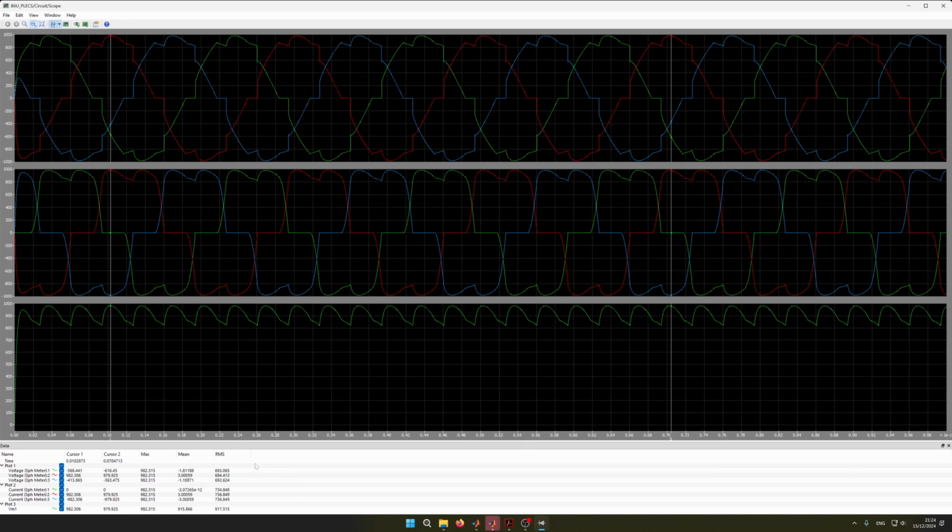Now, if you see, we also still have the RMS cursors here set up. We see there is a part of voltage lost due to the AC side impedance. For example, it's not completely 700 volts, but less than 700 volts. And also the effect on the DC voltage is seen here. It says 917 volts.